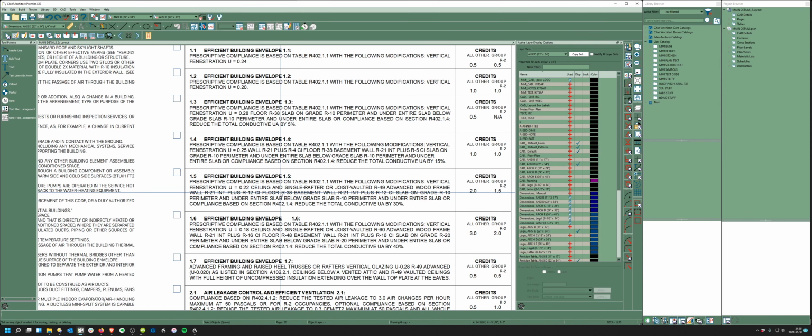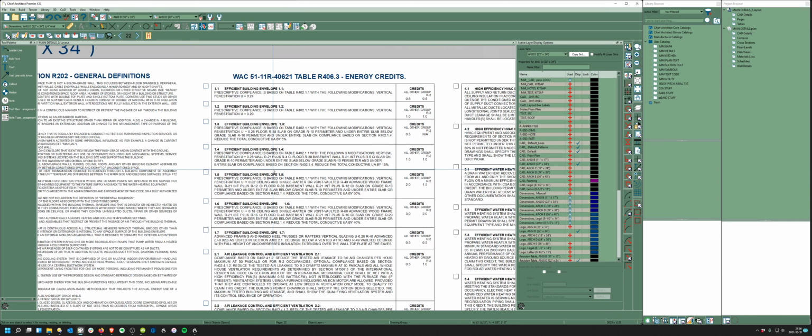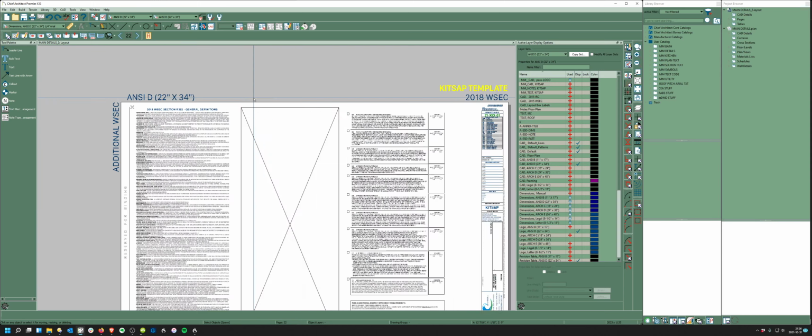Instead of R30 in the basement or in the floor system, R38. So basement wall is either going to be a 2x6 up against the concrete or some rigid thickness outside of the concrete. So some of these costs more right up on the front end. Just getting windows down to that size are more expensive. But that's part of the way they're trying to corral the building process in Washington State into compliance. So you have to add up to 6 credits mostly for a normal house. ADUs are popular and they only need 3.